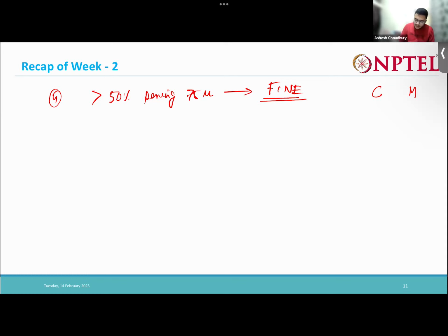Now our prefixes are determined. Then what we need to do is determine our plasticity index and liquid limit. So we take a certain amount of soil that is passing through the 425 micron sieve, and in that 425 micron passing soil, we do the liquid limit and plastic limit experiments to determine our plasticity index and our liquid limit.